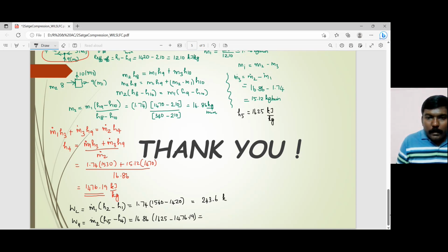This guy is in kilojoule per minute, because it is in kilogram per minute. Okay, so how about the next one? 16.86 multiplied by 1625 minus 1476.19. So that is 2508.94 kilojoule per minute. So the total work input is WL plus WH.